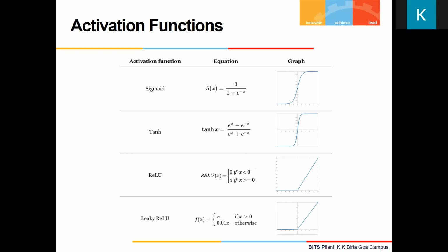Now, I don't have to go with that also. I will show in the coding later. I can go with a smaller number also, but I need to put the so-called saturation logic to counter this overflow issue. That logic will be checking, because internally I'll be using a large value. Output of my adder will be high, more number of bits will be there. That output I will check whether it is larger than the maximum value supported by this bit width. If that is the case, I will saturate it and send it. We'll see in the code.